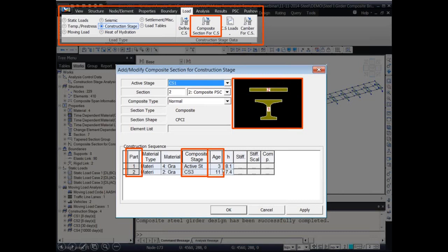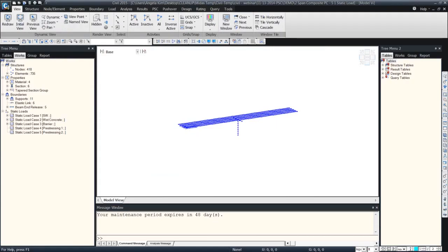So basically, age can reflect the duration that falsework is kept. If it's a precast, you can increase the age to a large number so that the stiffness is for sure what it is once it has already reached its compressive strength. So now I'm going to go to the program and show you one by one.